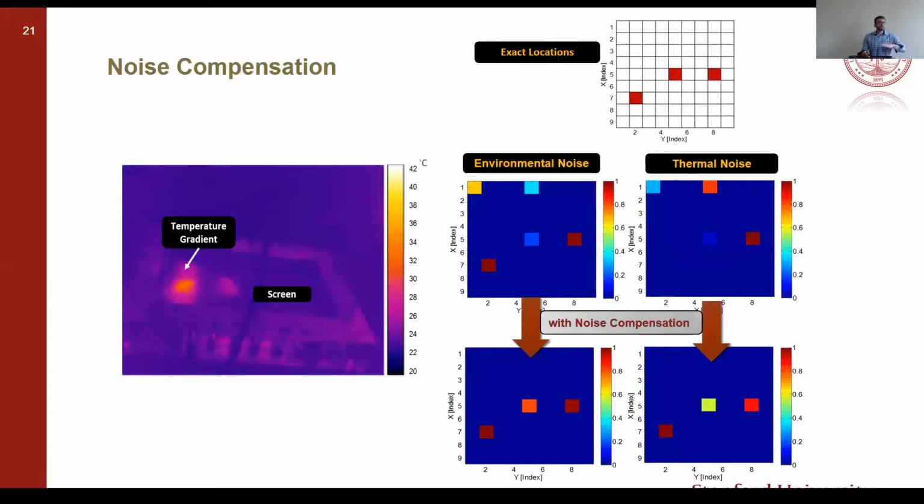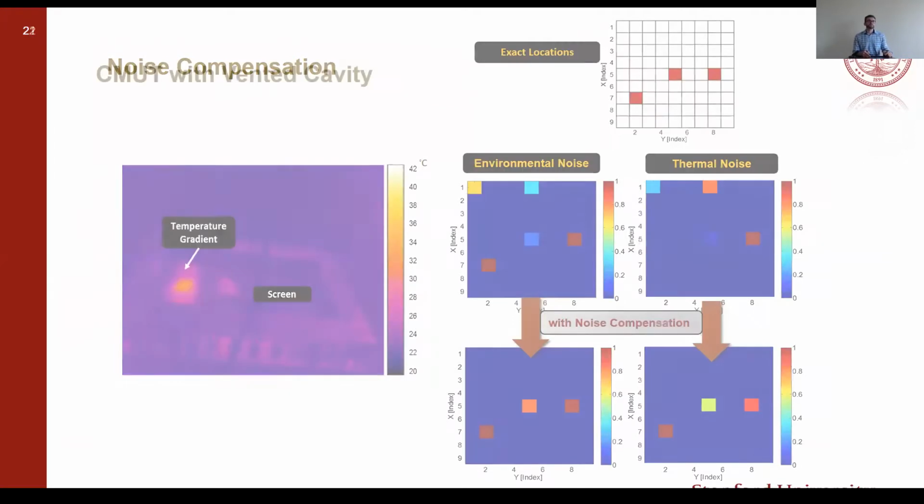As you can see, it can increase the temperature of the plate decently, which can alter the propagation characteristics of the long waves or the guided waves. Or you can imagine that this screen is integrated with a lot of ASICs and electronics, and they heat up, so the temperature of the screen is not uniform. The question is, how would it alter the signal you measure, and how would it alter the localization? In the results on the top you see it will make a difference. However, with the noise compensation techniques we studied, you can see we can recover very, very well.